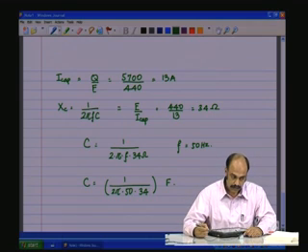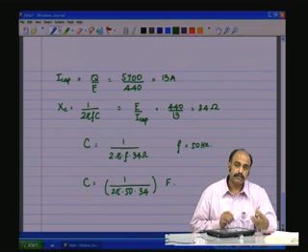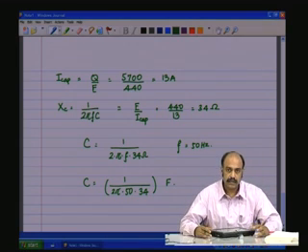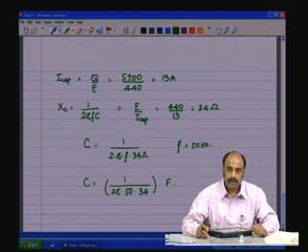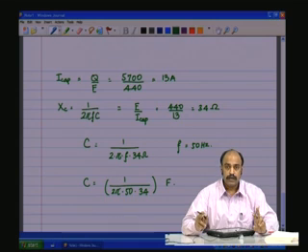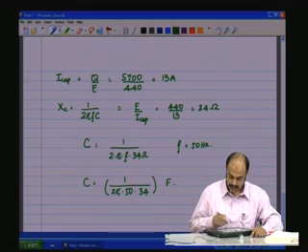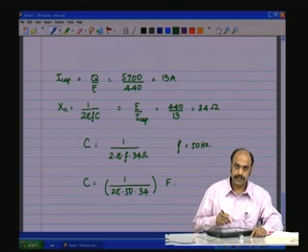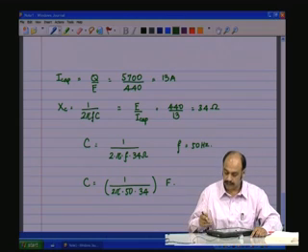So this is the way one goes about calculating the capacitance that needs to be connected to the three phases of the stator of the induction motor, if the induction motor has to be used as an induction generator supplying a standalone load not connected to another source, so that the reactive energy can be drawn from the capacitance, which can be used for maintaining the rotating flux.